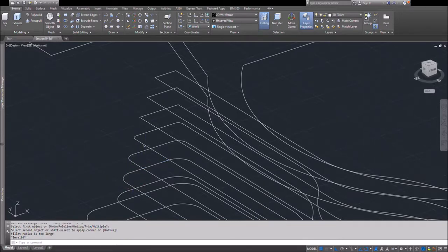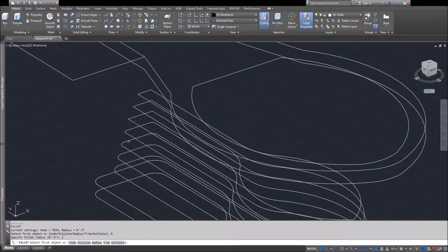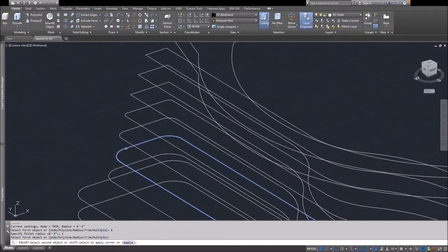So what I did was I drew the rest of it, the portion of the polyline that didn't exist, that extends underneath the tank, and I joined it together with the original polyline, and then I copied that down, because if you look at the edge of the bowl or the seat area, it does extend down vertically, sort of like a lip or an overhang around that perimeter. So I took that profile and lowered it, copied it down about 1 inch or so, 1.5 inches, because then again, once I make that profile and you make that surface, it'll create a sort of lipped surface there.